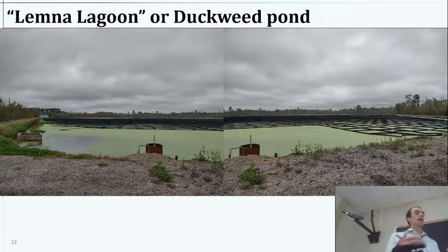There's organics in here. So what's interesting is if we were to look in the distance, it's kind of hard to see, but over in this area, there's actually some fountains. So there's a corner of the pond where you've got aeration. So that's where the wastewater is coming in, and you've got this aeration zone, and the water will kind of hang out there for a little while. So you'll have some aeration treatment, and then it's going to be just slowly working its way through the rest of the pond. And the residence time for this particular pond was about 90 days.